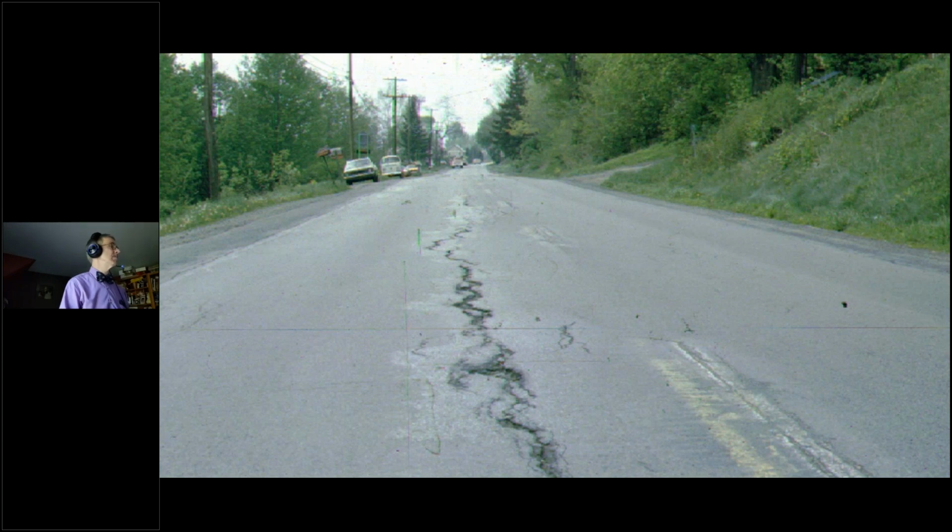A mill and overlay, approximately maybe the 24-inch band, right? Come in here and mill out a strip, like when my pen wakes up here. Now let's make sure the pen's working. Yeah, there we go. Mill out a strip, fix that strip. Okay, that's a possibility. Yeah. Patching with a cape seal, full depth repair, grind and patch, overlay, a huge number of choices.